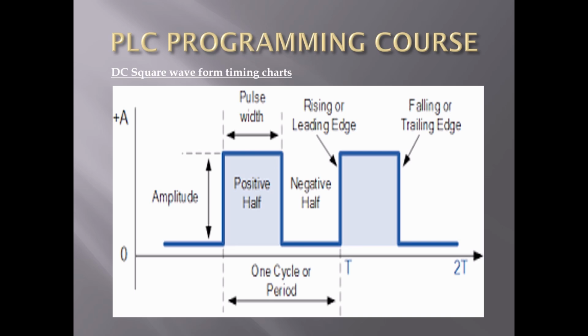Now, if this was in the case of an encoder, then let's say your encoder has 1,000 counts per revolution, then this square waveform would happen 1,000 times for every revolution of the shaft of the encoder. In a normal DC system, the steady state of 5, 12, 24 would just be a straight line. If you see ripples in that line, that's noise on your power lines, but basically it should just be steady state.